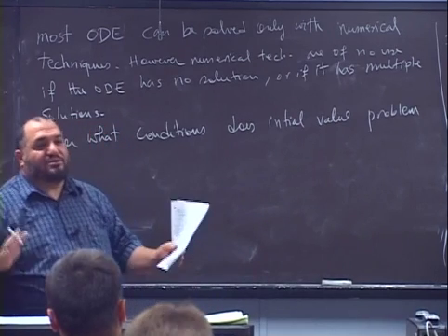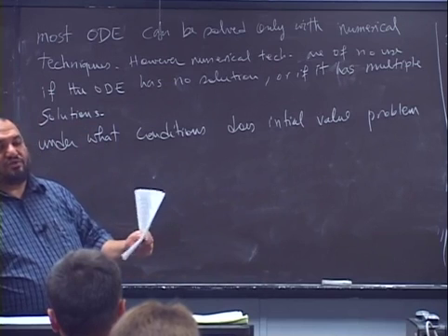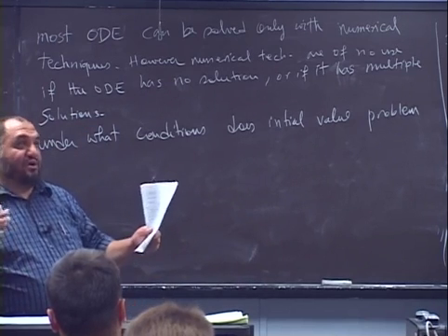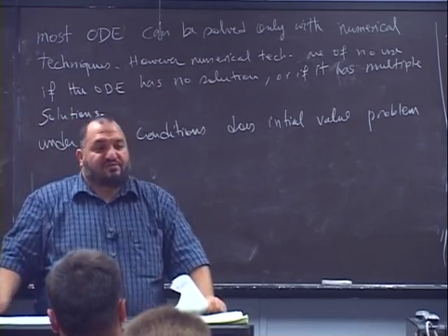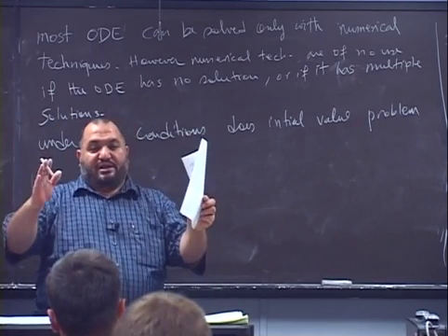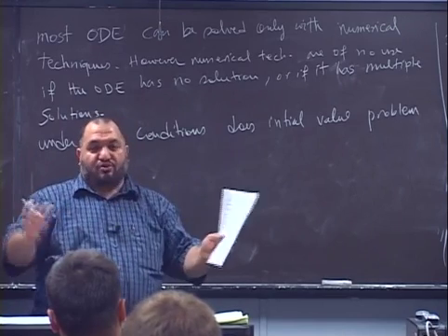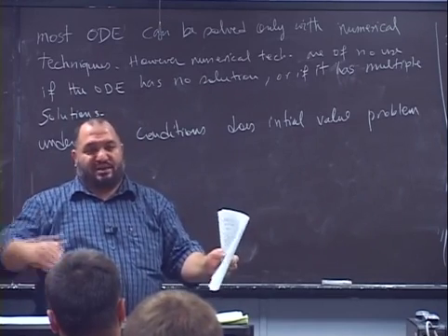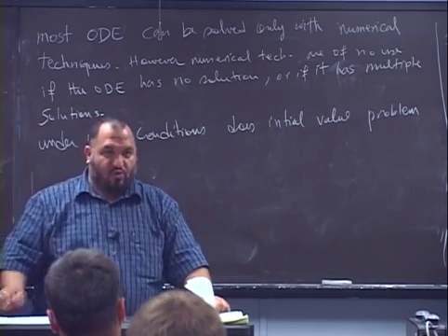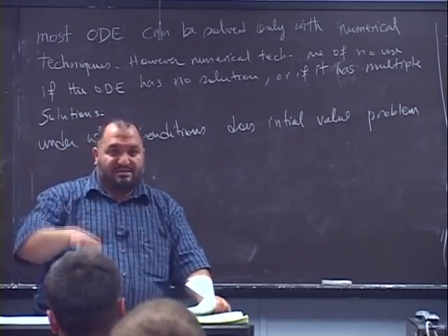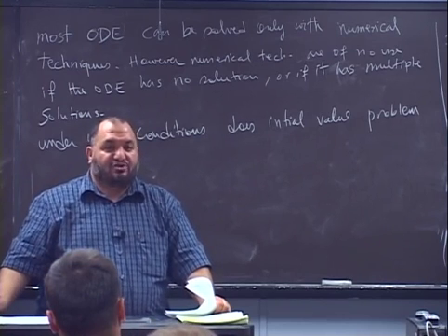If you are talking about solving the differential equation inside some domain or a boundary, let's say we are solving the heat transfer equation inside a wall, and this wall will have dimensions, so it will have x equal to -a to x equal to a. So we have to specify the temperature at both boundaries and at initial time.